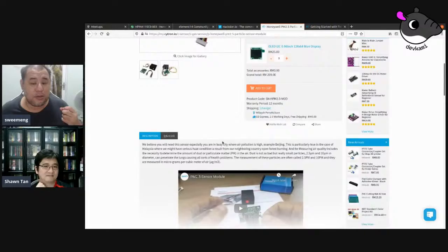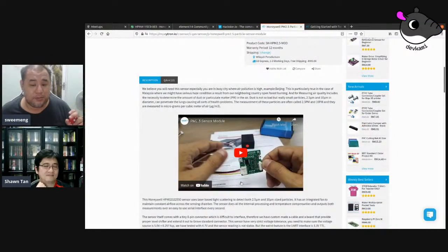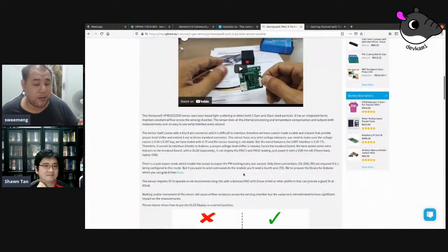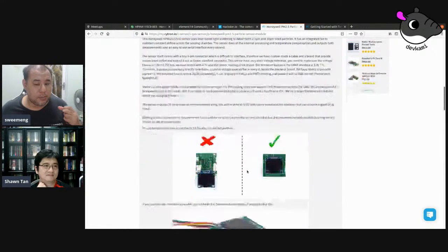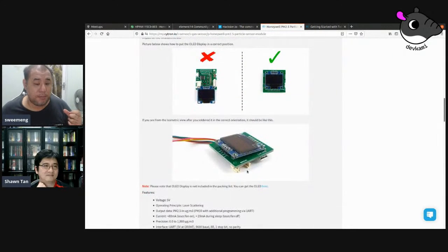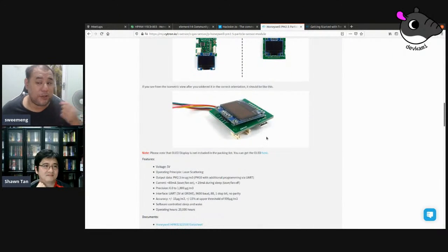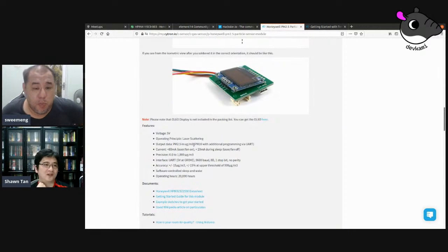But either way, even though the UART protocol and all that is reasonably simple and also digital, you don't simply plug it into a computer, because USB is actually a very complicated protocol, and you need to tell them whether it's a serial or something else. So USB is a very, very complicated protocol. You need a proper microprocessor with a USB stack in there. Correct. Which is why you need something like that.